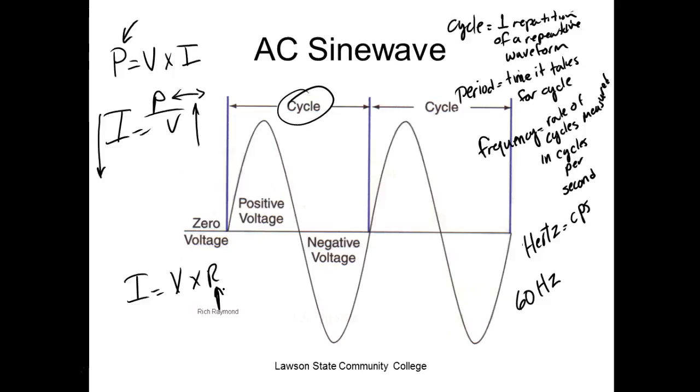And of course, when it gets to my house, what are the two primary voltages we get at our house? Yeah, what we call 120 and 240. So all our high wattage loads run off of 240. Keep the amperage down, which means I can use smaller gauge wire, which means now I can run it through my walls instead of running it underground, right?